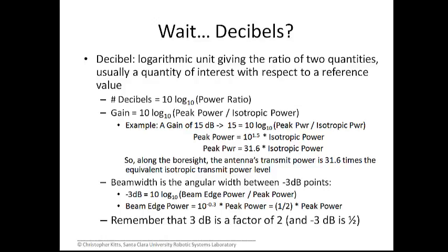Decibels itself is a logarithmic unit, and it allows you to logarithmically compare two quantities, and that's what we're doing. We're comparing the power out of our real antenna at a given angle and comparing it to the equivalent power that you would get out of this abstract notion of the isotropic or purely omnidirectional antenna. So the isotropic antenna is our reference in this sense, in order to establish a comparison, and a logarithmic unit of that comparison is the decibel.